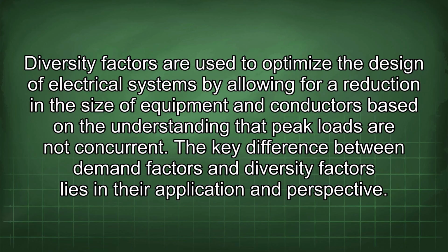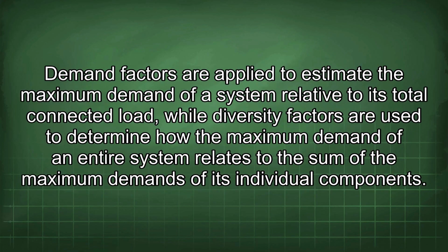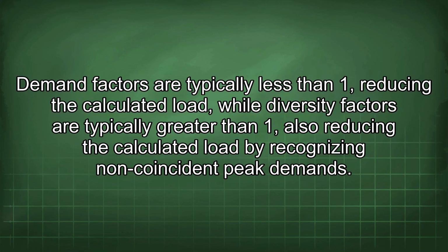The key difference between demand factors and diversity factors lies in their application and perspective. Demand factors are applied to estimate the maximum demand of a system relative to its total connected load, while diversity factors are used to determine how the maximum demand of an entire system relates to the sum of the maximum demands of its individual components. Demand factors are typically less than 1, reducing the calculated load, while diversity factors are typically greater than 1, also reducing the calculated load by recognizing non-coincident peak demands.